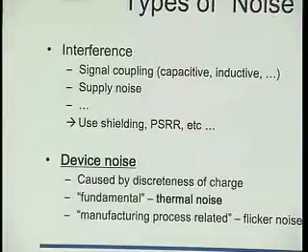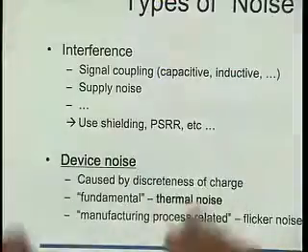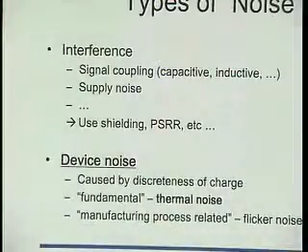If we do everything right, I mean, we use shielding and so on, in principle at least, we can always beat down these forms of noise, right? We can use more blocking on our power supply. We can use separate power supply for the digital and the analog ports, even maybe several power supplies for different parts of the analog circuits. And there are lots of ways we can deal with them.